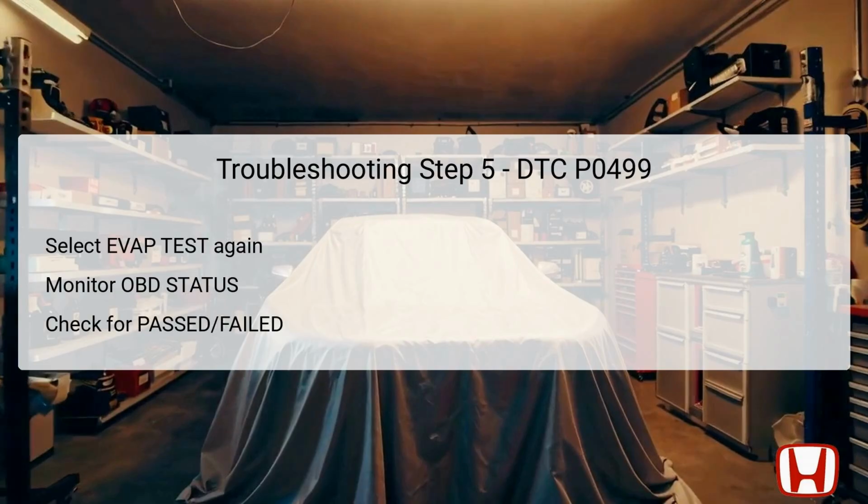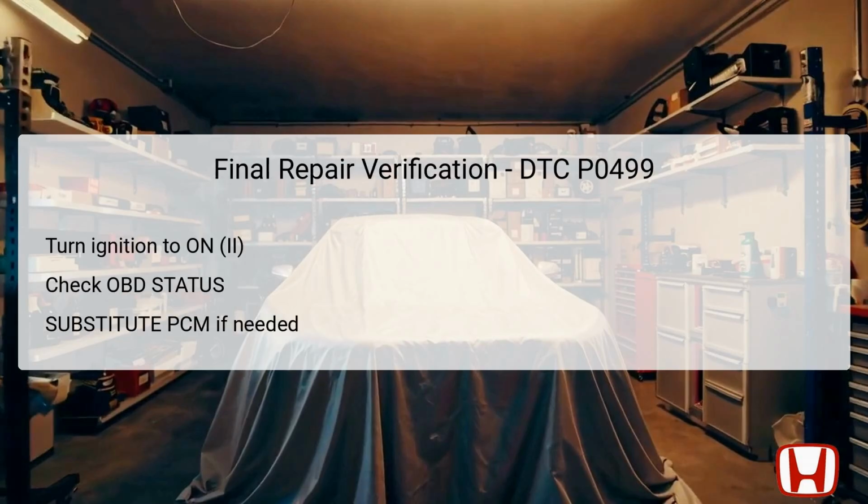If the test indicates not completed, it's essential to meet the appropriate test conditions before retesting, as environmental variables can affect the outcome. For final repair verification after troubleshooting DTC P0499, begin by turning the ignition switch to the on position once again. This allows you to check the OBD status using the HDS for any lingering issues.